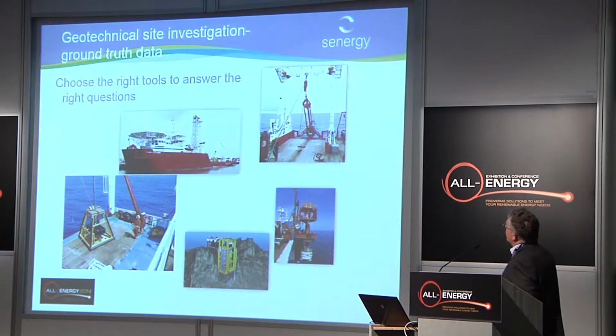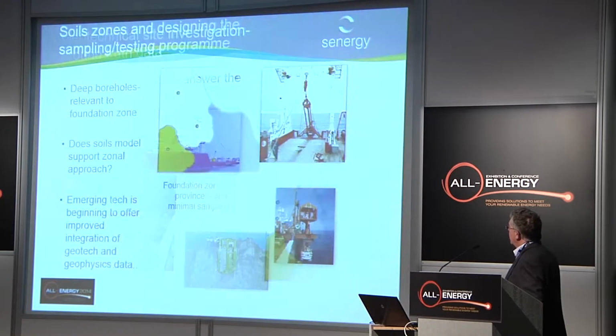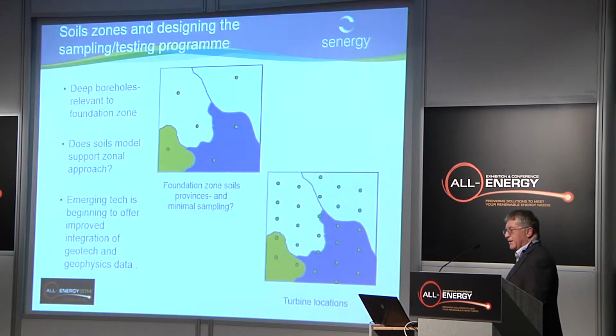Yeah. So, your geotechnical site investigation, ground truthing. We need to use the right tools again to gather the information we need at the stage we need it. And these are shallow data sets for cable burial and deep data sets for foundation assessment. And then where we space these things out, this is the big question of zonal versus turbine-specific sampling.